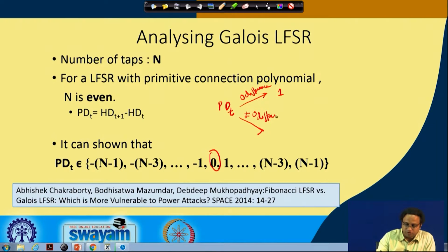And observe that the non-zero difference levels can go as high as up to n minus 1, okay. So, if you are doing this attack on real power traces, then you can intuitively understand that it will be hard for you to distinguish these cases because they are almost close, okay. Whereas, if you have got some jumps which are as high as this, then they are more discernible, more distinguishable from this zero level, okay.